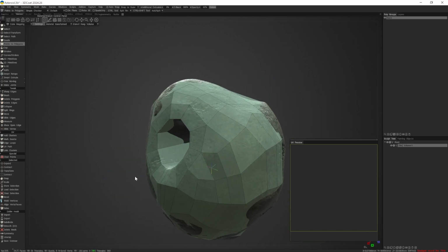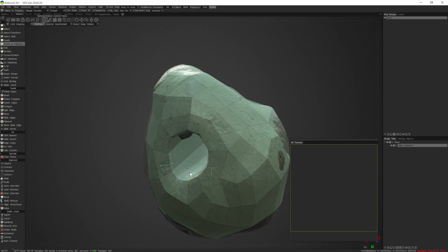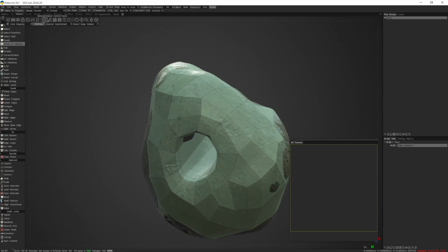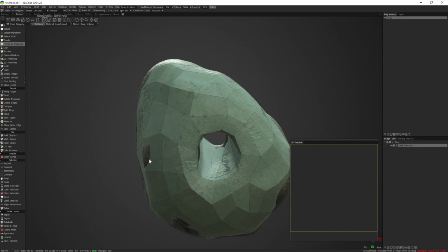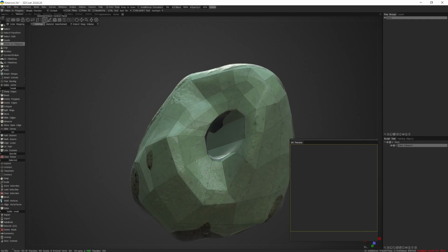All right. Cool. So I'm just going to hold down Control because I'm in my points to polygons tool. By the way, I was right-click dragging to move those verts and drop them onto the other pieces. You might find that you accidentally left-click out of habit and create these random points. If you do that, you want to get rid of them. Hover over them and press Delete. They'll turn yellow. You just press Delete to get rid of them.